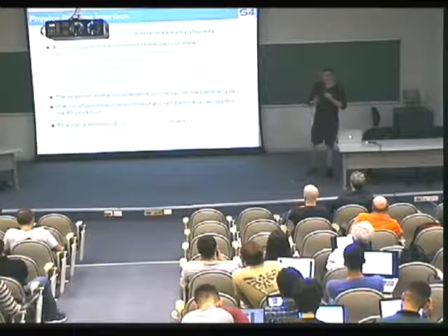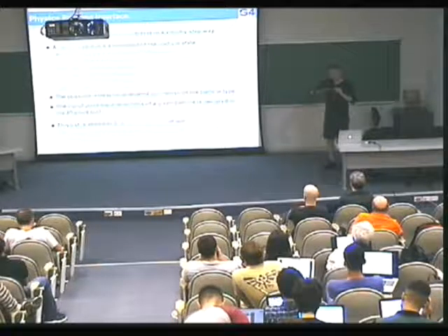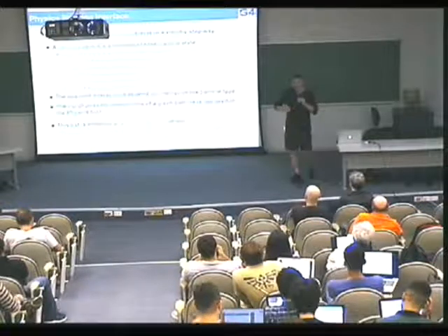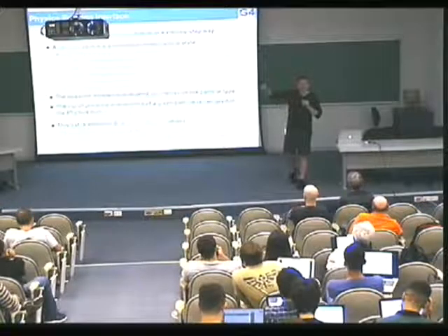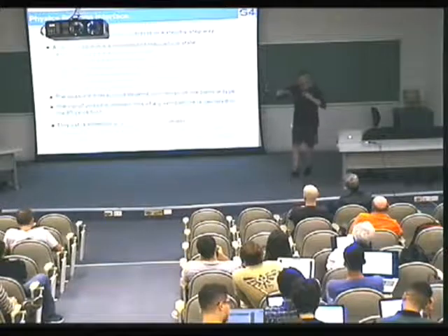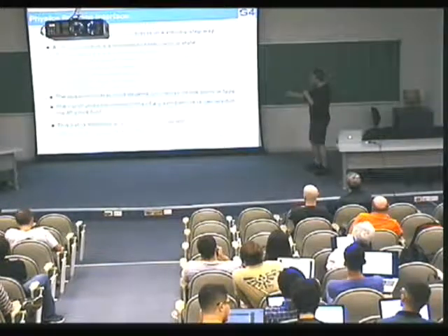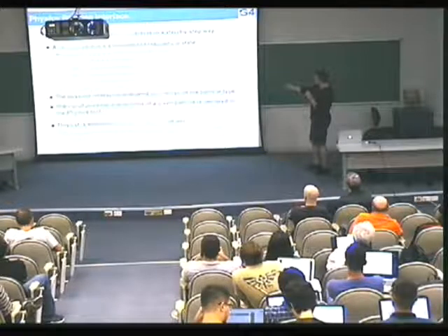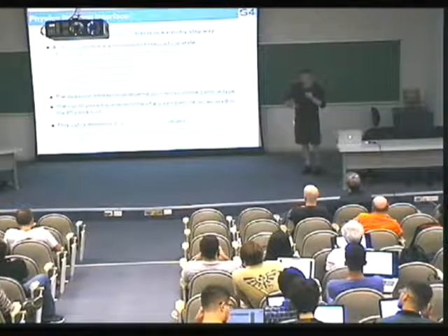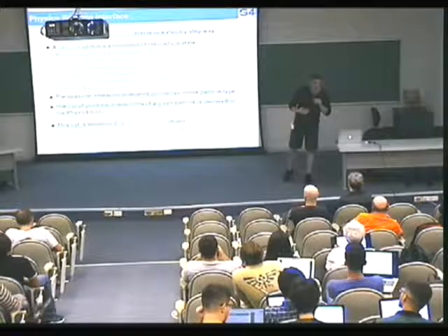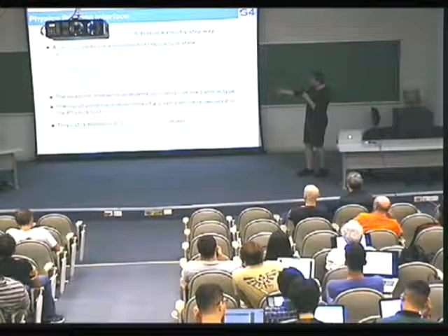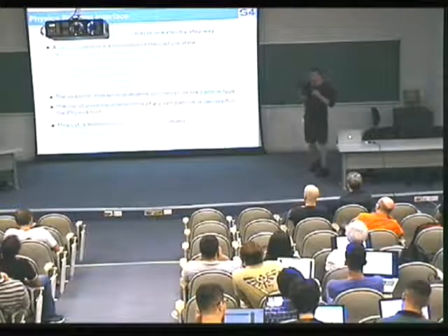One set is static. Okay, it does not change at all during the tracking, and actually these properties are exactly the same for all tracks having the same particle type. What I'm talking about is these static particle properties, for example, charge, mass, and so on. You can imagine each electron has exactly the same. So these are described in Geant4 in the G4ParticleDefinition objects.